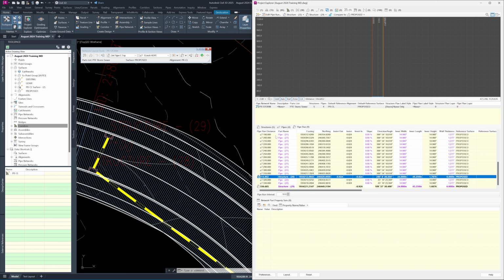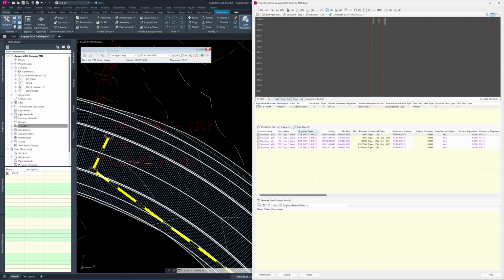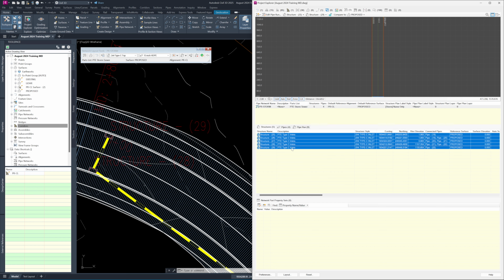Like the pipe names, well, here's what we've been using this for quite a bit. This is the description. There's no way in our template currently to actually define this description to be what we want it to say in the charts. So if you highlight all of them, you can right click and say set description, and let's say we want this to be modified. Oops.